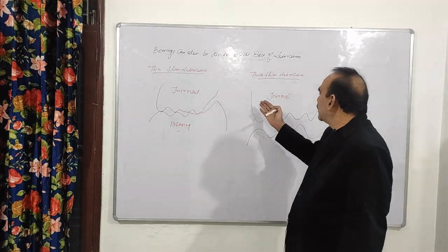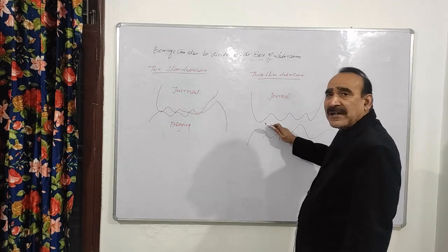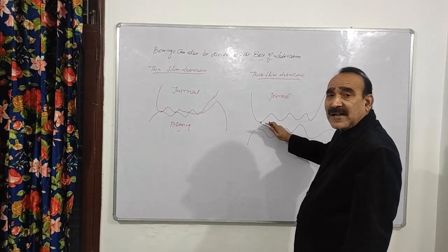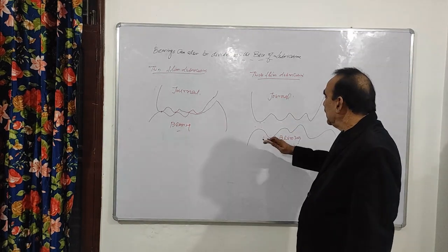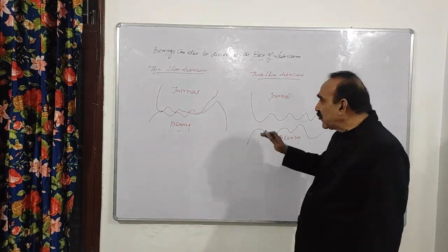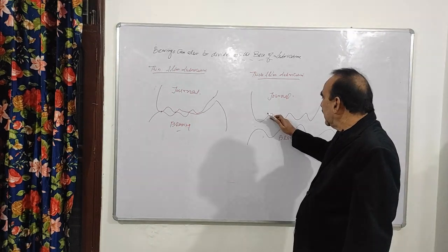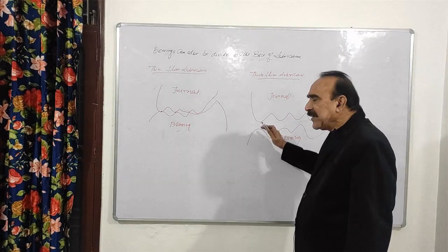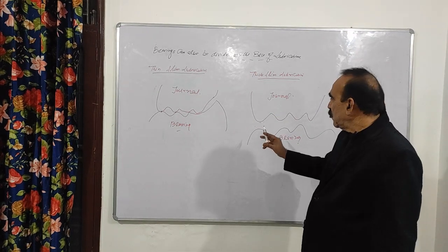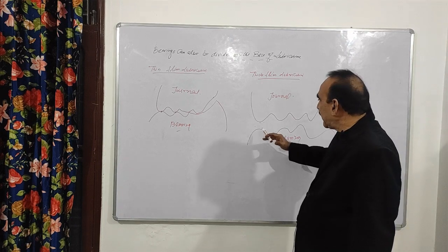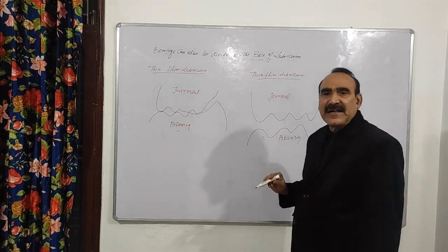What if we come to thick film lubrication? In thick film lubrication there is complete separation of the journal surface and the bearing surface, or you can say the contact area between the journal and the bearing is completely filled with high pressure lubricating oil which separates both the journal as well as the bearing, right?